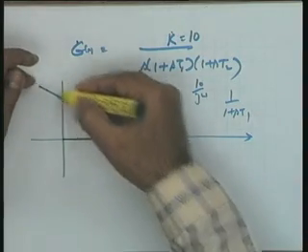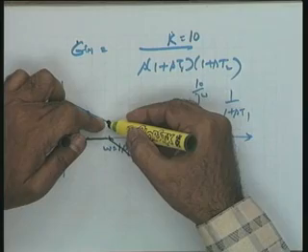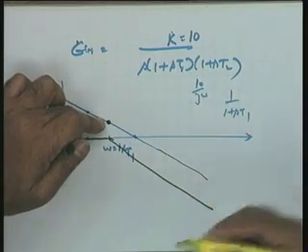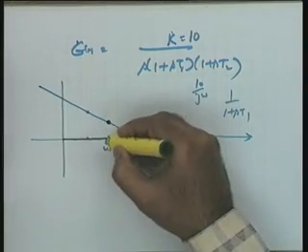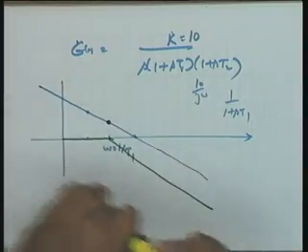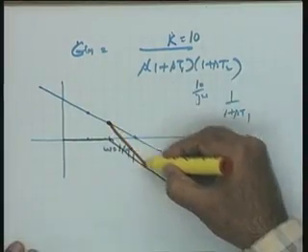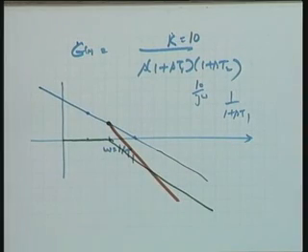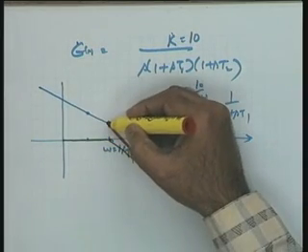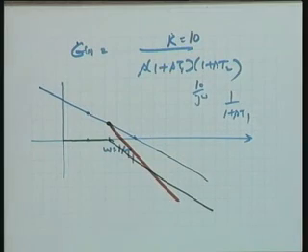So, this original line was earlier minus 20 dBs per decade. From this corner frequency, the slope changes by another minus 20 dBs per decade. So, at this particular corner frequency, you change the slope by minus 20. So, in total it becomes minus 40, and hence the addition of the two is a line of minus 40 dBs per decade passing through the corner frequency taken on this particular line.